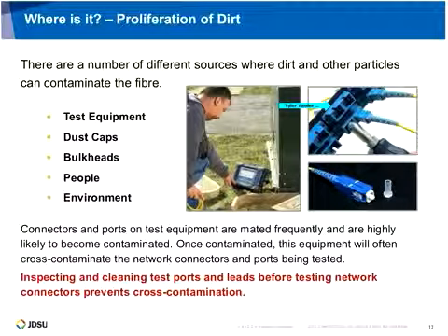And if there's contamination on that other side, plugging a clean connector into it is going to have just as much impact on that connection, because one half of it was already contaminated. Once you plug that in, you're actually going to be transferring that contamination to the other side of the connection as well.